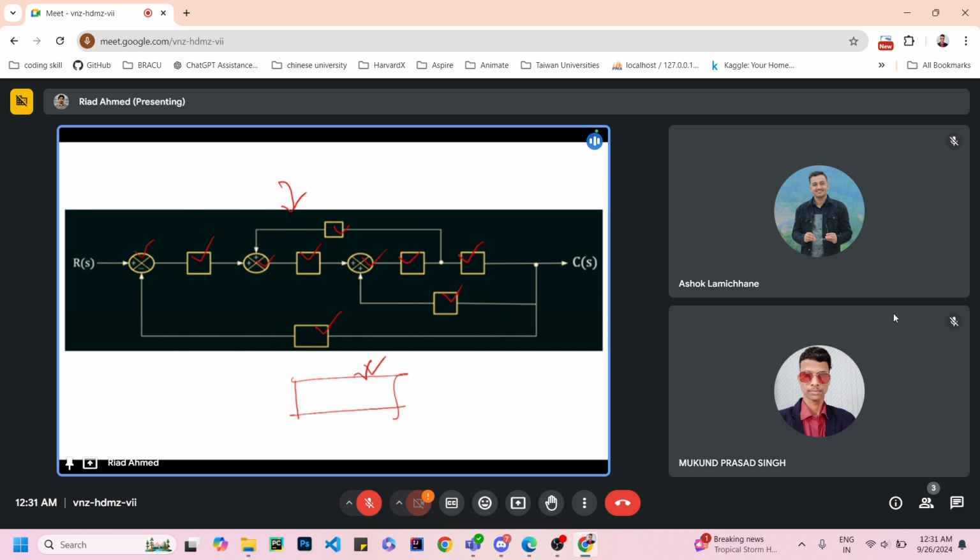This is simply like in an electrical circuit, where you have different types of resistance in it, right? You can convert all of those resistances to an equivalent resistance, which does the same thing that all of those resistances combined do. So this is called equivalent resistance. Similarly, a single block can be calculated which can do the same things that the whole diagram is doing.